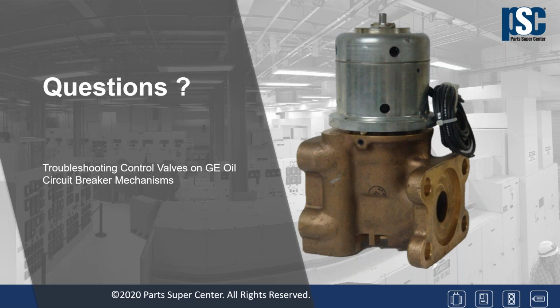So the procedure to test these valves is, we get the correct series resistors for each of the windings, because there's no way to electrically test these at the minimum, maximum, and nominal control voltages without having the correct series resistors. So that's the very first thing we do, is we obtain the correct values for the series resistors, and then we go ahead and connect up the leads.